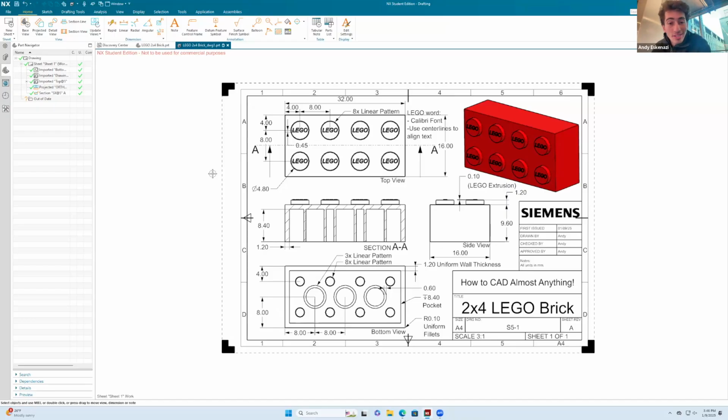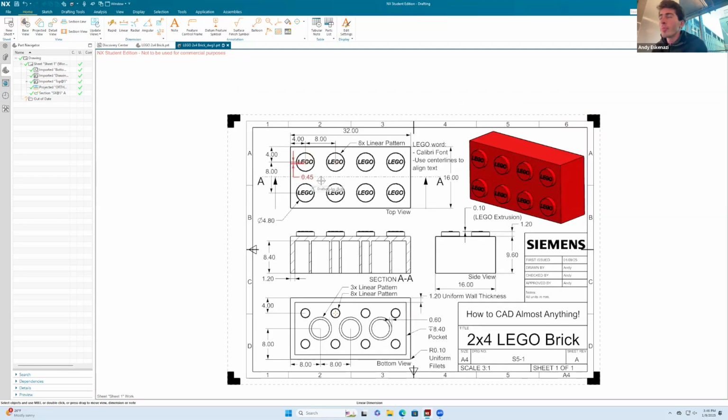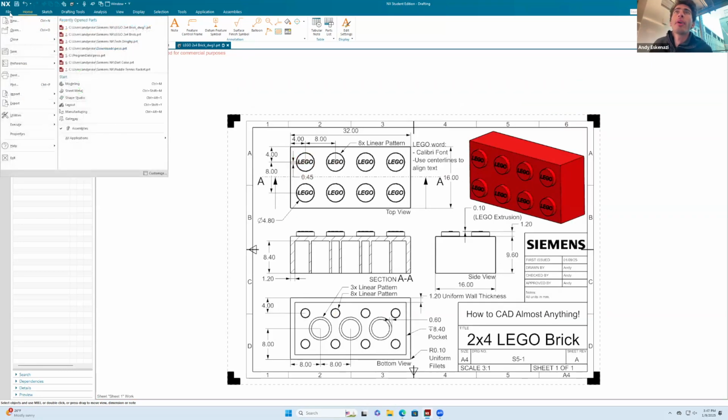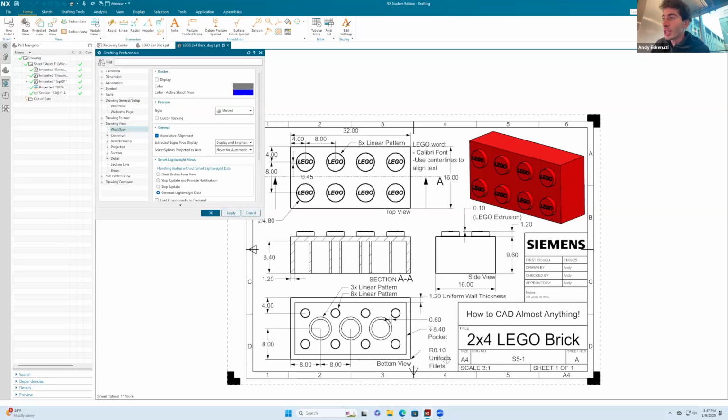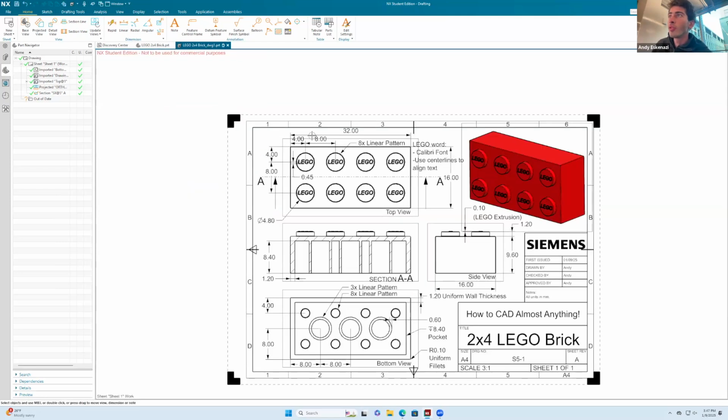Okay, just two last notes before we're done. So here it is, our mostly completed drawing. What I will say from here is that you go to File, Preferences, Drafting. You saw me manually having to change all of these dimensions. The reality is that you shouldn't have done it. This is stuff that I learned after the fact that would have helped you a lot of times. In particular, if you go here to Workflow, you see by clicking Display, those boxes appear here.